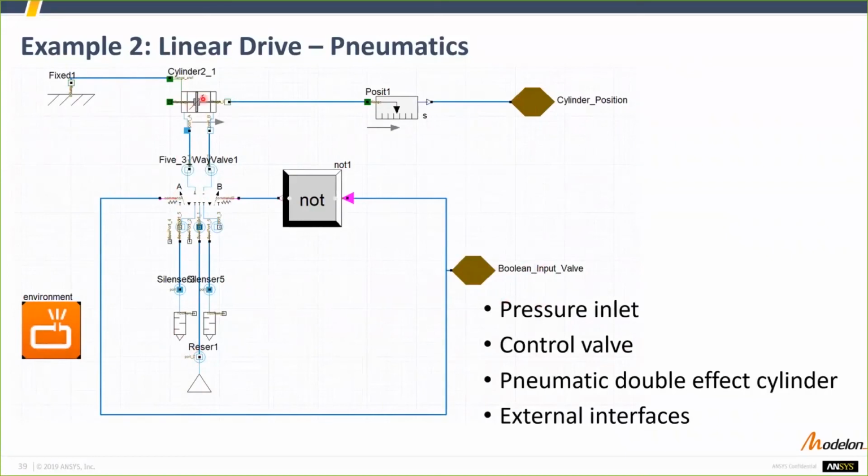The cylinder is modeled here with some cushioning, modeled with this row here, and you have the valve here, which takes either from a reservoir, which directly takes the air from the environment and compresses it at the given pressure, typically 7 bars, and gives it back through the silencer, which also has a restriction inside because the silencer usually has a restriction to reduce the noise generated at the output of the gas when releasing the air, typically into the environment.